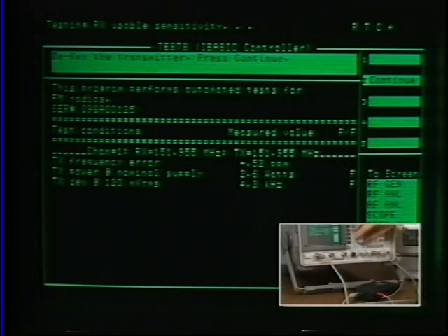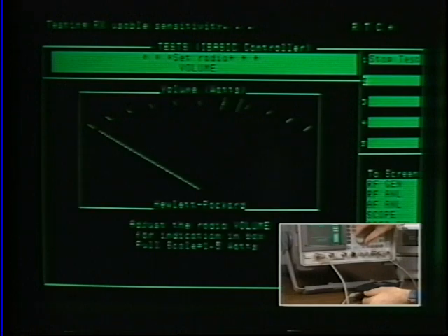Dekey the transmitter, set the squelch to minimum. If the audio volume needs to be set for any type of test, the 8920 will display a bar graph to aid you in setting that level.